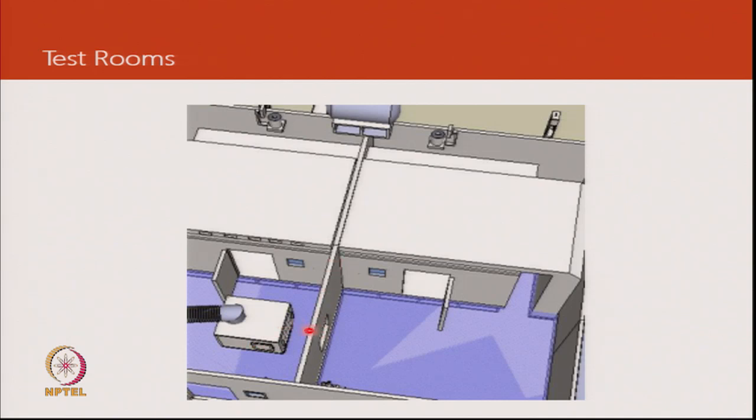So this separating wall, and let's say this is a window unit, it gets connected to this wall, and then there is another side where we have a duct. The duct connects to the supply air portion of the unit, and inside that duct there's a chamber which has nozzles in it. The pressure drop across the nozzles gives us a very accurate indication of the total airflow.